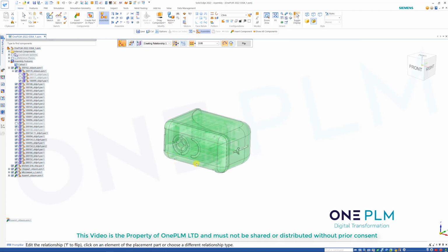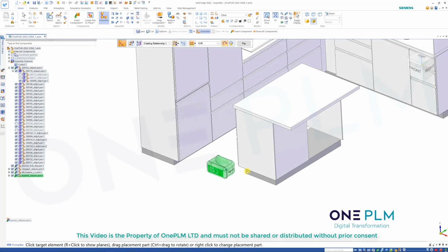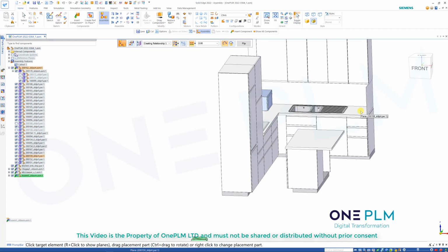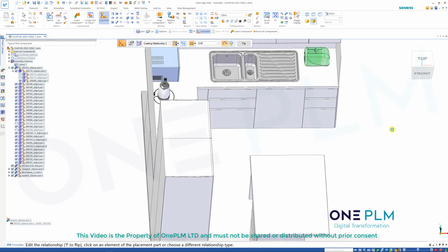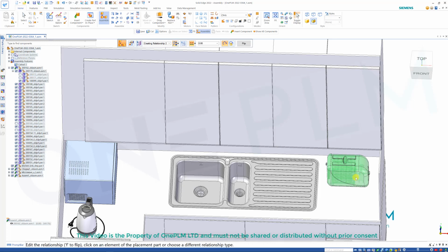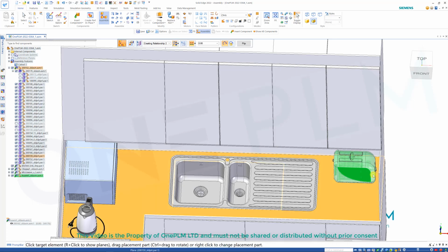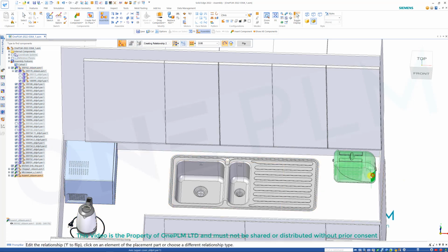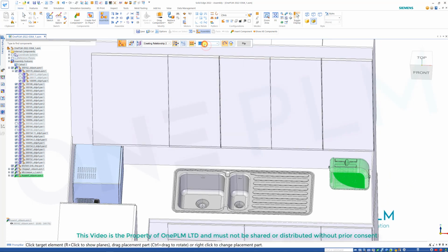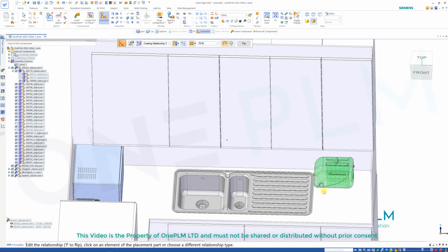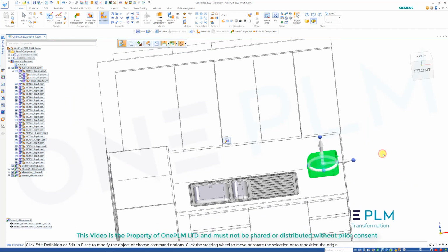And this looks like the base. I can't see any feet, so I'm just going to do that straight down there. Pop it in this corner this time. That's good enough potentially. Okay, I might actually just do that face with a, say, 75mm offset to the back face and use the F key and then just drag that to position there. There we go, looking good, looking smart.